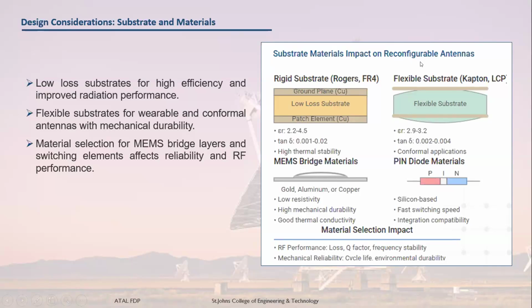You might have heard about wearable antennas, textile antennas. Even on our pant, an antenna can be printed. What is the substrate for my pant? Jeans. Jeans is a substrate. So by changing the material which I use as a substrate, by changing the properties of that substrate, like epsilon r, which I can change from 2.2 to 4.5. Because if you look at the frequency of operation, epsilon r also comes into the picture. Those who work on microstrip antennas know that the frequency of operation is related to epsilon r, the dielectric constant. So if I change the dielectric constant, can't I change the frequency of operation?